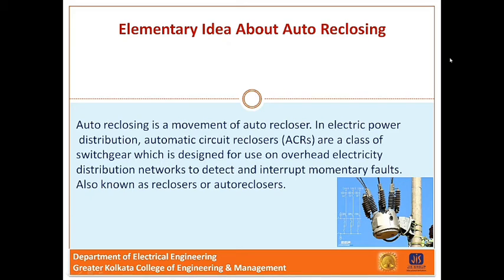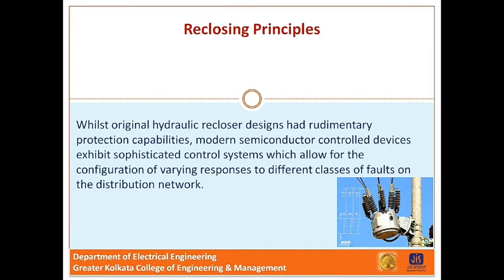On a three-phase circuit, a recloser is more beneficial than three separate fuse cutouts. For example, on a Y to delta connection, if cutouts are used on the Y side and only 1 out of 3 of the cutout fuses open, some customers on the delta side would have a low voltage condition due to voltage transfer through the transformer windings. Low voltage can cause severe damage to electronic equipment, but if a recloser were used, all three phases will open, eliminating the problem. Next is the reclosing principle.